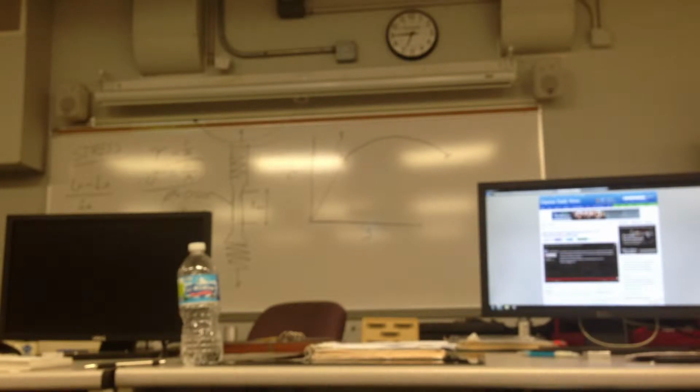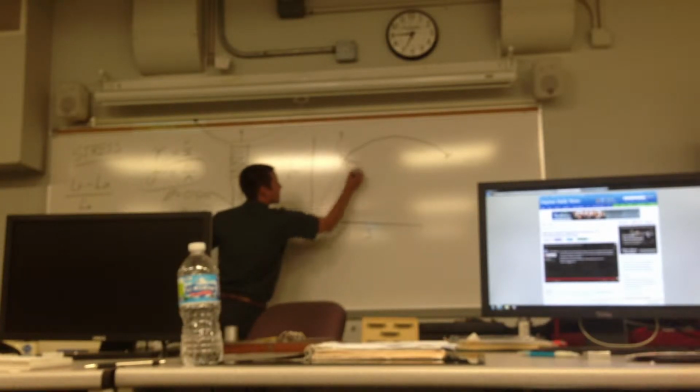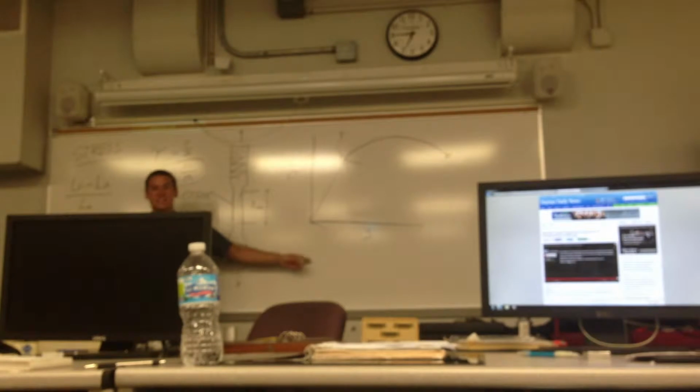Right now it's at this angle, and I pull it a little bit, it goes right back, right? I go a lot, I yielded it. It's not going back, right? So that means I've taken it into the plastic region. So all of this through here, that'd be the elastic region.